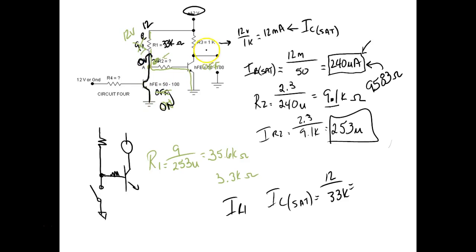If that puts 0 volts right there, what does this transistor do right here? It has no base voltage. So what would it do? It cuts off. And this is really, really standard. So now I'm turning this transistor off and on electronically. Who has to move that switch? You do, right? What moves this switch right here? 12 volts. Where does the 12 volts come from? Well, it might come from another transistor. It might come from another circuit, right? You understand? It might come from me pressing this little old button right here on my power supply, right?